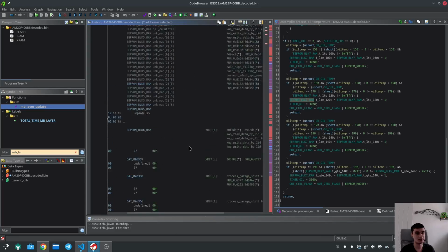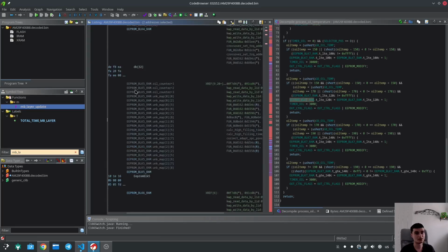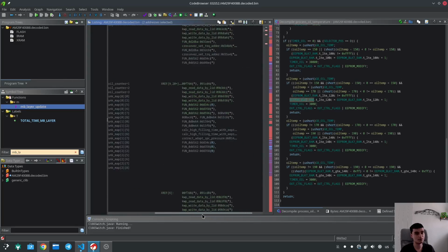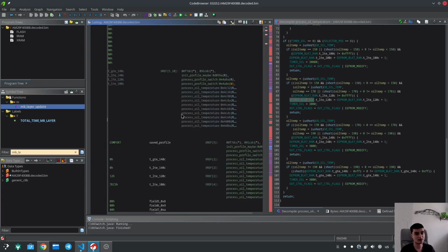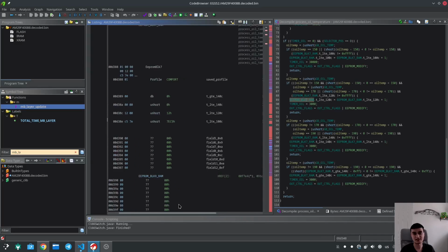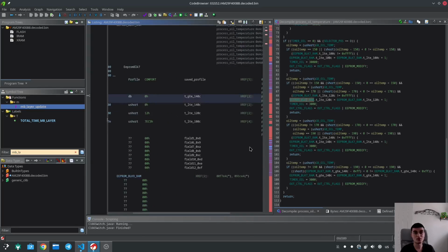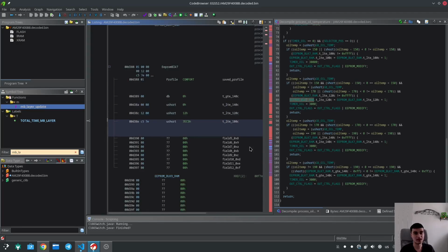Compare that to a couple of EEPROM blocks above, and you can see, for instance, EEPROM block 5, which is for some, I think it's torque converter adaptations, I'm not sure, but you can see it's read by the KWP read data by local identifier function, which I identified as that. So this can be accessed through diagnostics, whereas this area here cannot. So I don't know why they left this counter, or what the purpose of these counters is, but it's interesting because it is gathering statistics on how long your gearbox is operating with certain oil temperatures.